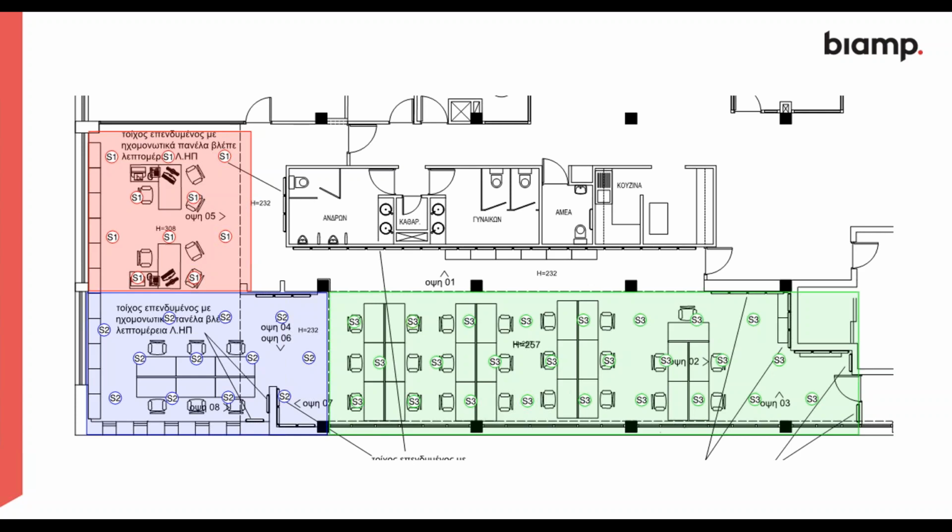Can we integrate to a fire alarm system? Which means if we get a line out from the fire alarm panel. Well, in theory, yes, you can integrate to a fire alarm system and play sound through the emitters. However, they will form absolutely no part of the fire alarm system whatsoever, because they are not made to any EN or similar standard.